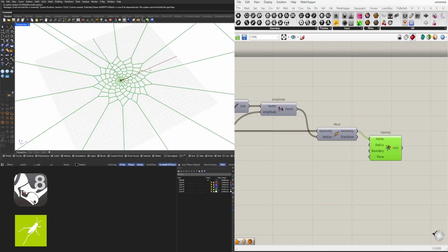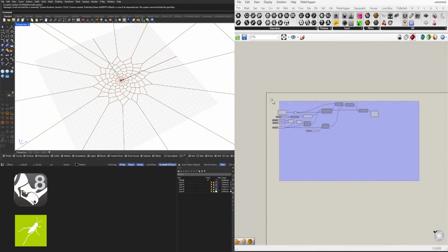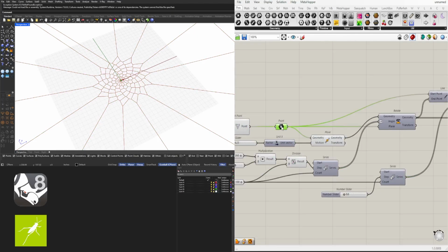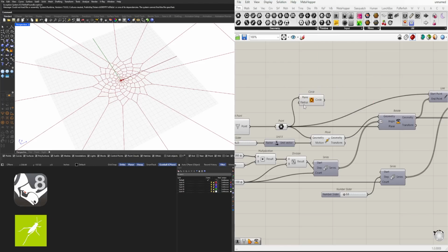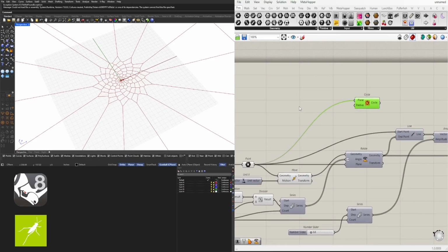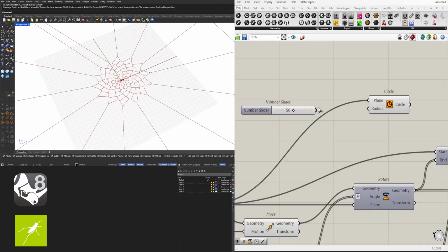Here is a way to extract. It doesn't even have to be this pattern. It could be any pattern. Extract a pattern using a boundary polygon. It could be a circle. It could be whatever polygon you want. So what we'll do here is go to our initial point, create a circle. We'll change the radius. We'll go to, let's say, 50.